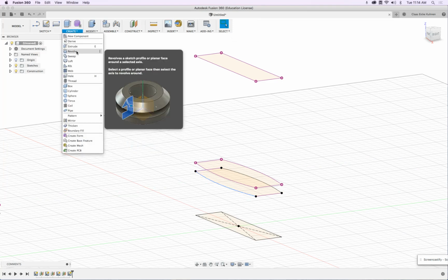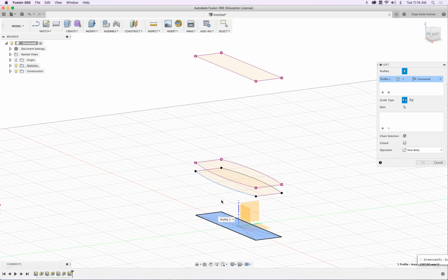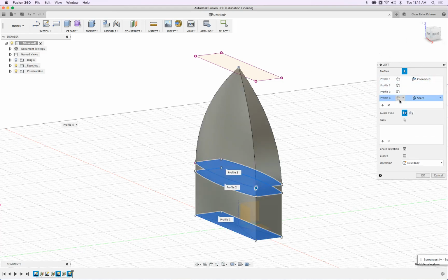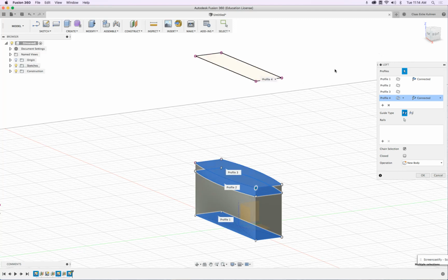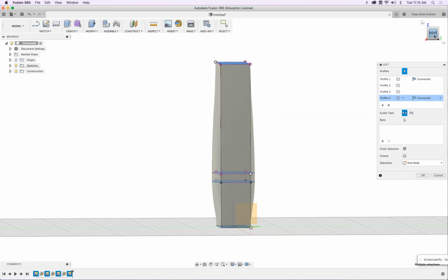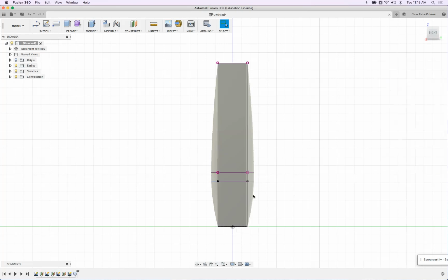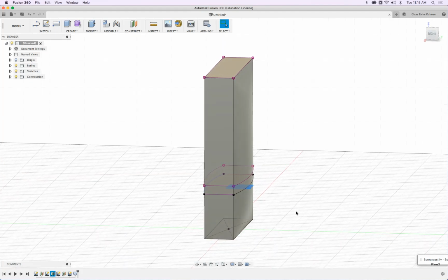Then if we do a loft, click, click, click, click, whoops, not point, sketch. There we are. Very good. Now the shape, how this bellies up, we can essentially define with where is this and where's this other construction plane, height-wise.